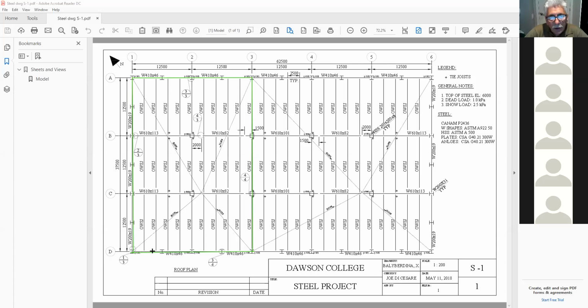But why are they still under the 6,000? It says minus 125. Which one? The exterior ones. Oh yeah, that's because on these ones, the joists are going to be sitting on top of the beam, I just finished explaining that. Here the joists are sitting on top of the beam, and the shoe is 125 millimeters high, and therefore this beam has to be placed at minus 125. So when they put the joist, the top of the joist is at 6,000.